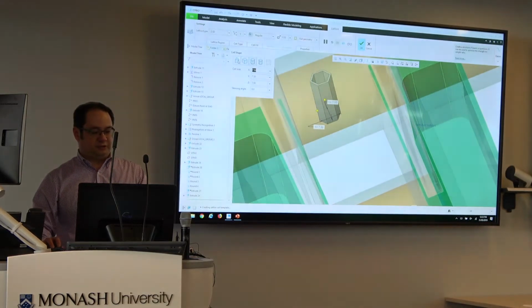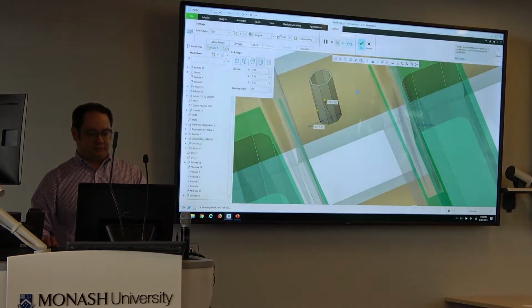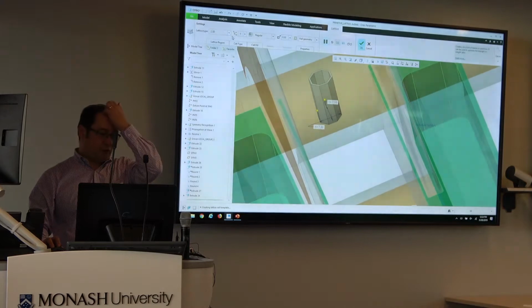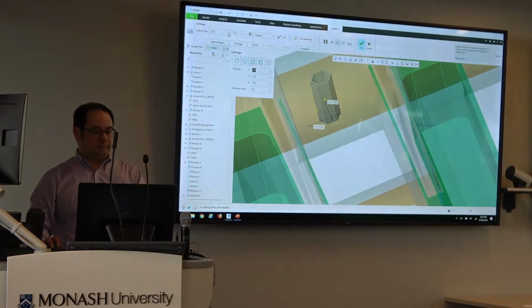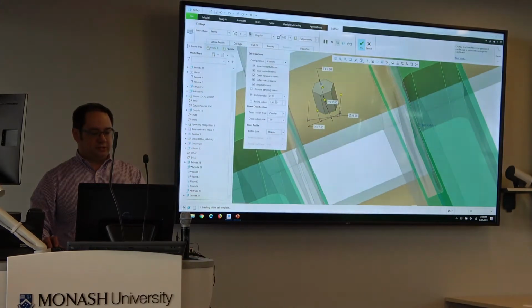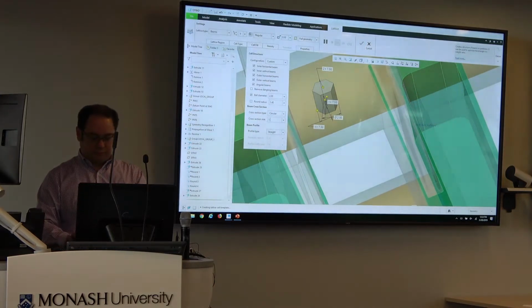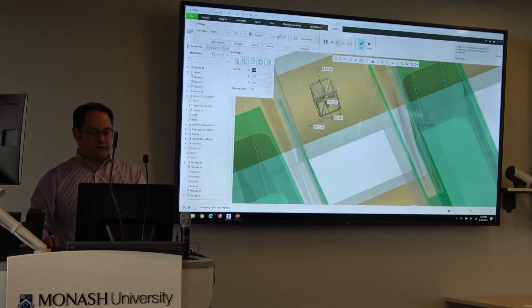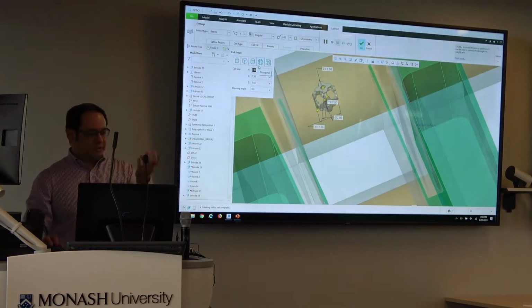So we've got all of our different cell types, you know, triangular, hexagonal, square, octagonal. So we can see all of those different shapes there, like so. We've been able to do that since Creo 4. Now we can go back in and maybe choose beams. So this is our 3D shape now. We just need to change the sizes of these. So we've got similar things again, hexagonal, square, triangular, octagonal shapes, like so, that we can fill in with a 3D lattice. We've been able to do that since Creo 4.